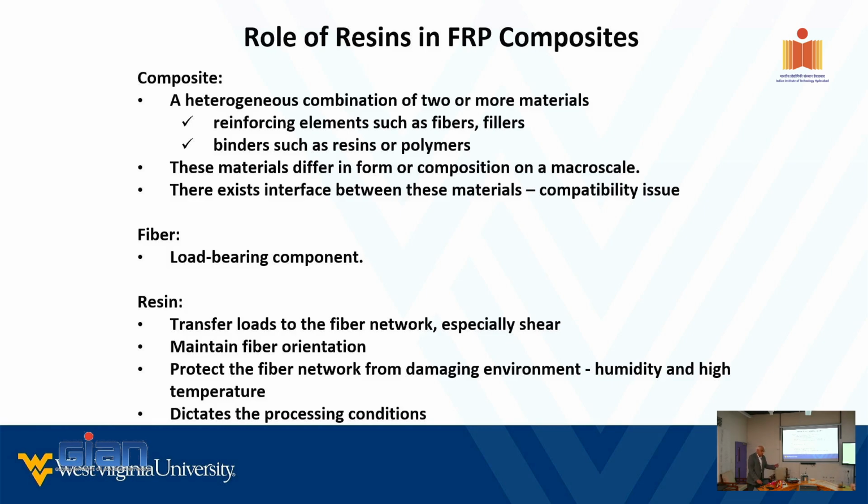If you don't, then these inclusions of the voids and what have you are fantastic stress concentration zones. That's where the crack starts. You don't see it with the naked eye. After about 5 or 6 years of service life, it will start to grow, and it will grow with time. That's called fatigue. Or it could be creep. That's why creep is called a static fatigue. I'm sure most of you